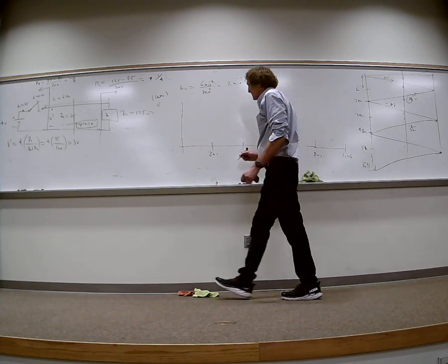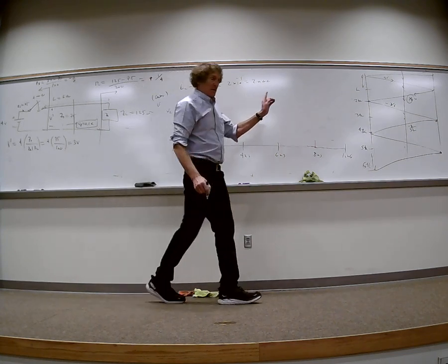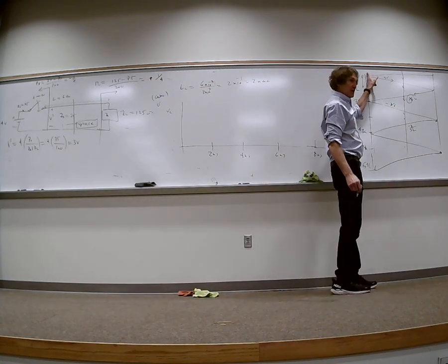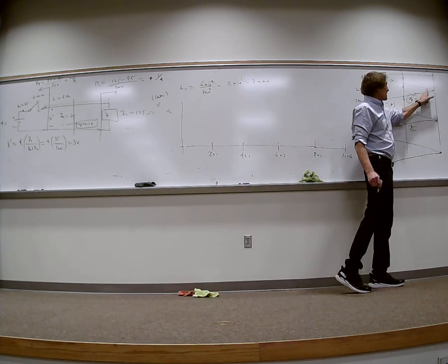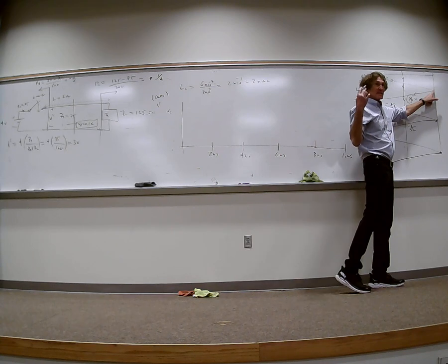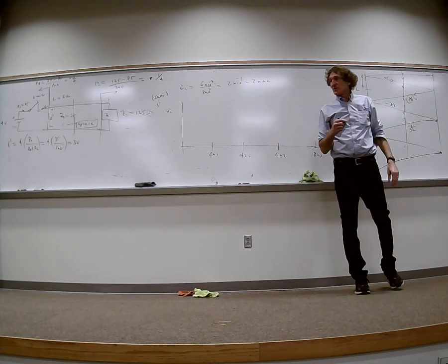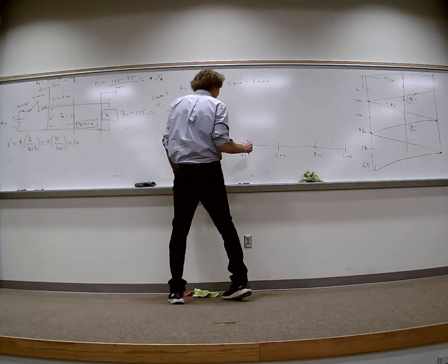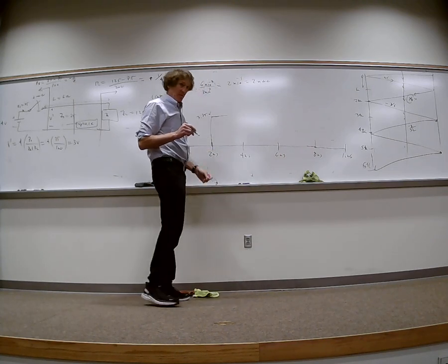Now you tell me this is going to be the voltage at the load. What happens? We start here, we've got 3 volts. It's coming down. It hits. There's 3 volts, but at the same time it hits, you have to add 3/4 on. Y'all follow me? So it would come down here, at 2 nanoseconds, and would immediately go up to 3.75 volts.